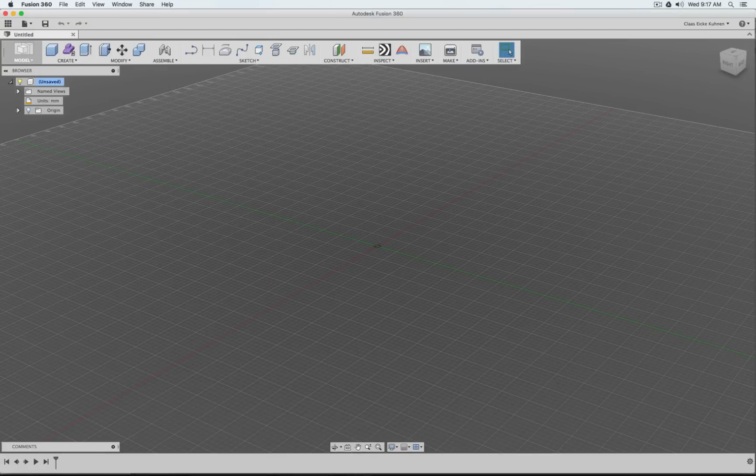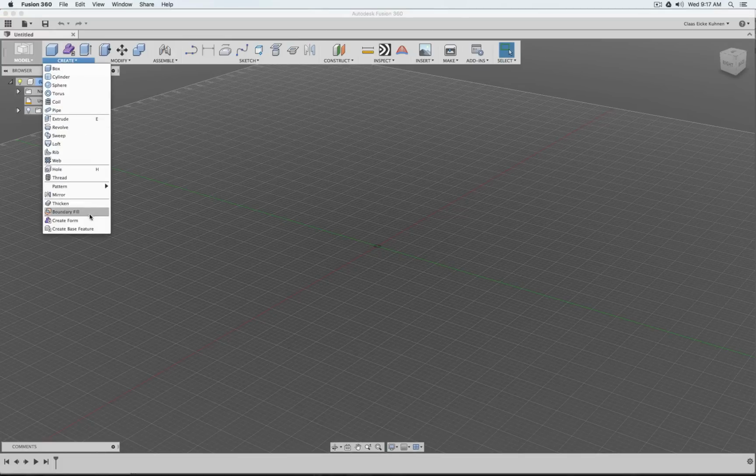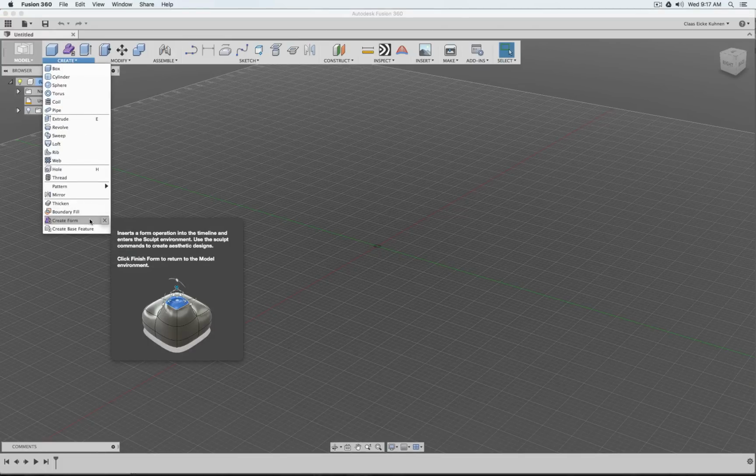Okay, so I would like to bring over the Blender model, which we exported as wavefront OBJ, and the T-spline module in Fusion, as you can see in this image, gives you the same subdivision surface sculpted technology we also can use in Blender.